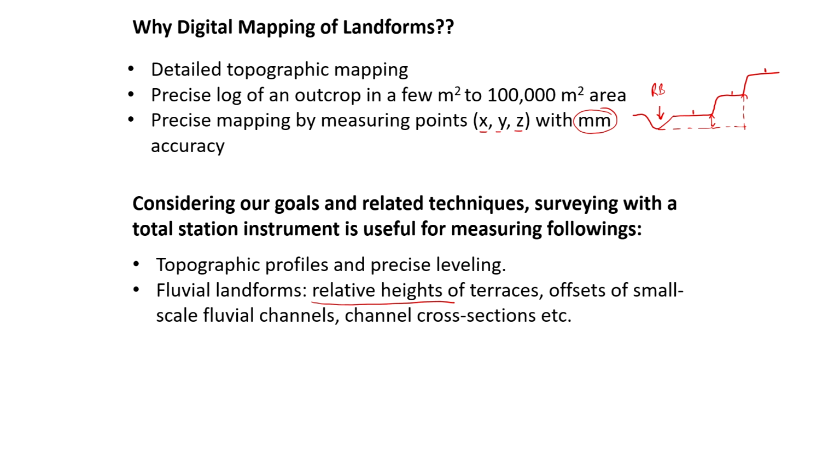height of any landform, then you can even use the benchmarks which are provided by the Survey of India. Or, since we are having a high resolution GPS antenna here, that is what we are using, differential GPS. So that will give you the height with respect to the MSL. So this also you can get, and also the coordinates with respect to north of a given particular point which you are measuring in the field.